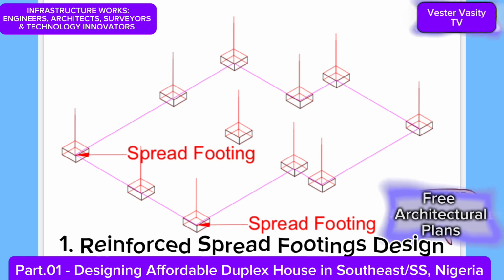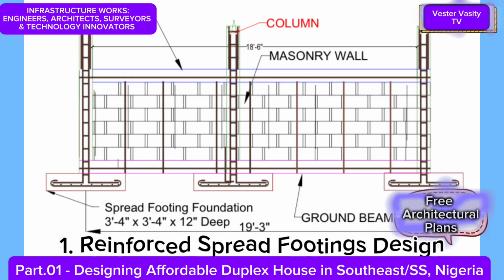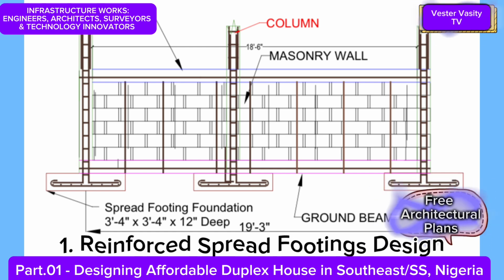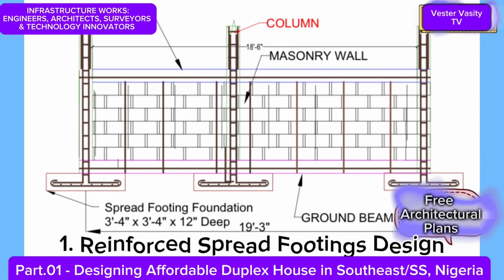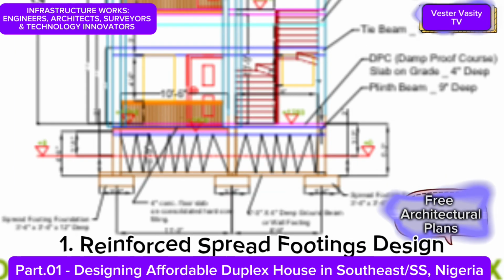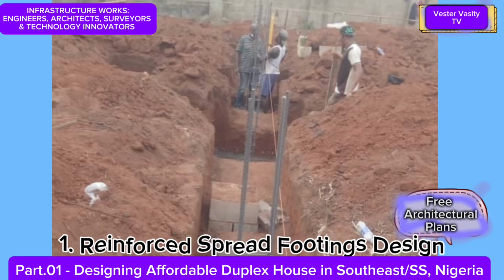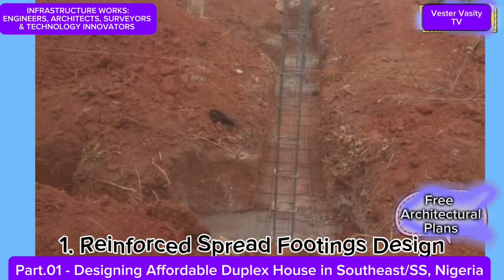The reinforced concrete spread footings are designed to support and transfer to the soil below the weight or the dead load, the live load, the wind load, and other anticipated loads from the columns, the beams, walls, and the roof above the spread footing foundation. The reinforced concrete spread footing foundation will be discussed separately in detail in an upcoming separate video presentation.